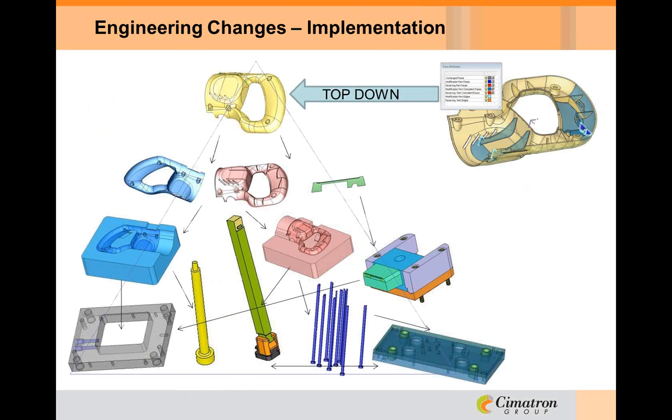Now, once identified, there still remains this huge task of implementing the change into the ongoing design. Really, the initial part data is at the top of a large pyramid, and the entire assembly has descended from it. So a top-down approach, where each successive part updates the changes above it, would seem the best plan of attack. And often it is, especially at the early stages of the mold design.